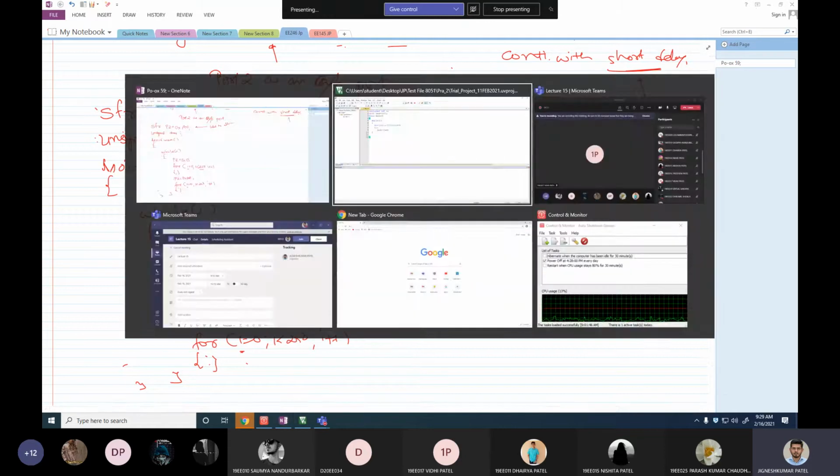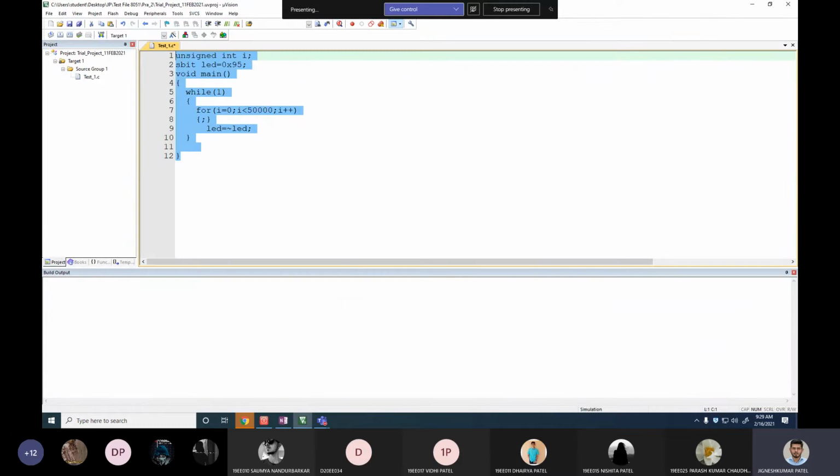So let's quickly execute this program. What I have to do is sfr P2 is equal to 0xA0, that's P2, and here I'll have 250 as the delay.